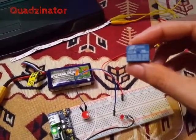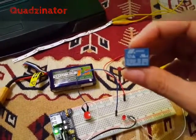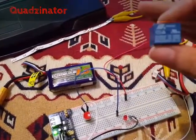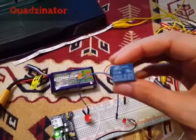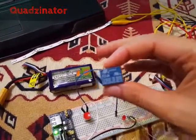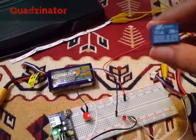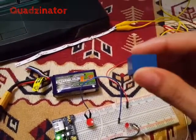And it has another purpose, which is protection. By separating high voltage circuits and controlling them using a small voltage circuit, we protect the small controlling circuit from any damage that can happen from the high voltage circuit. That's another application.